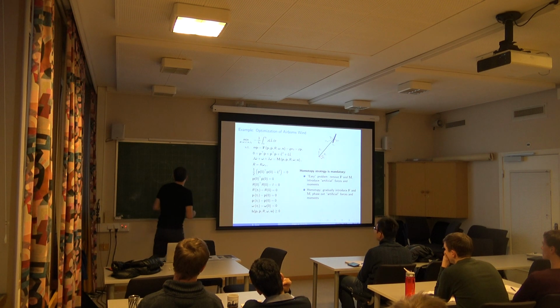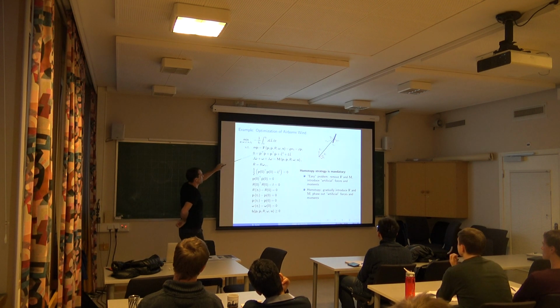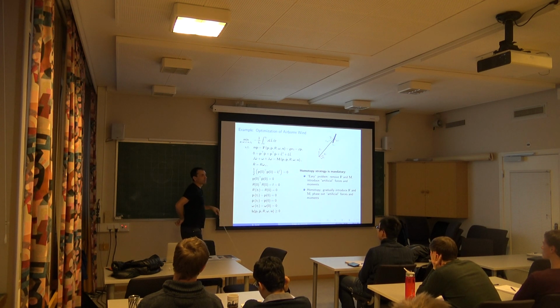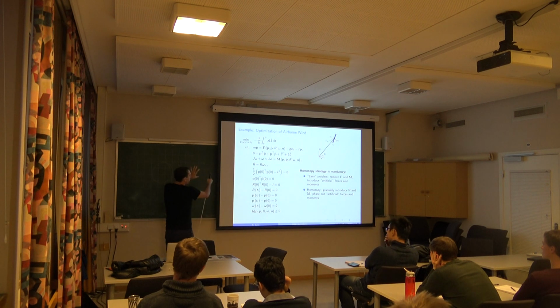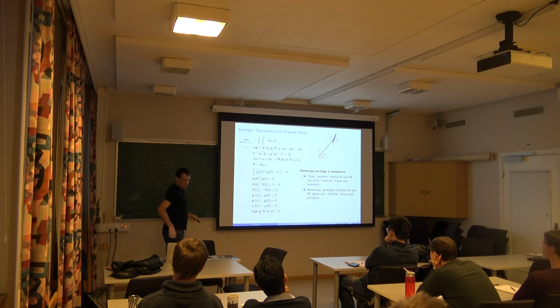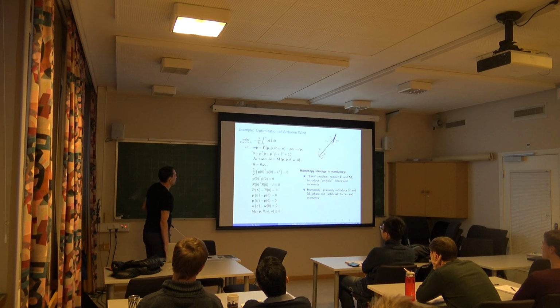And then we have a parameter that slowly phases out these forces and moments to replace them by the correct one, the aerodynamic ones. So our forces and moments disappear from the model and these guys appear. That's called a homotopy strategy. And if you do that, you actually manage to solve the problem.